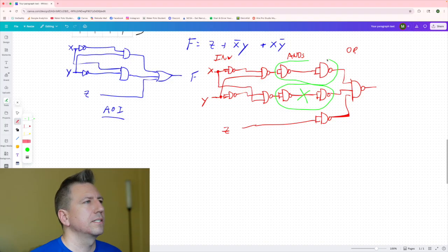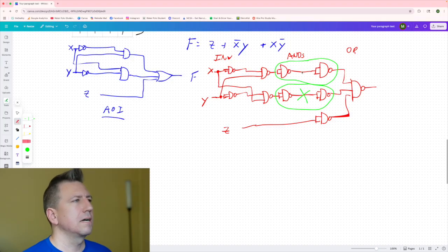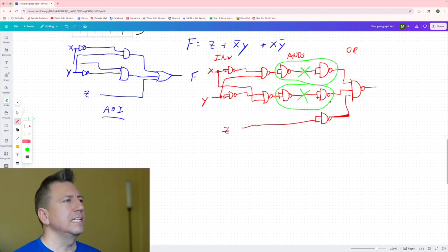And because we are an SOP, this is common. We expect these double inversions to show up in between our AND gate and our OR gate. Since there is no AND gate on the Z line, that one stays, so that inverter will stay there. It won't be canceled out by the inversion coming from the AND gate. Okay? So those are the only two that get simplified, that get knocked out, and so we end up with something that looks like this beginning section. Those get knocked out, and then we have that end section.